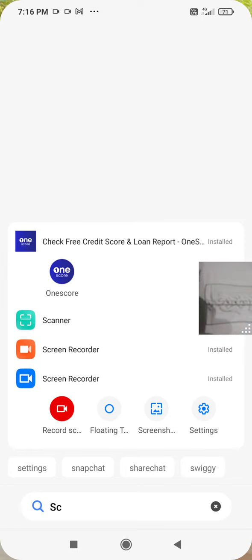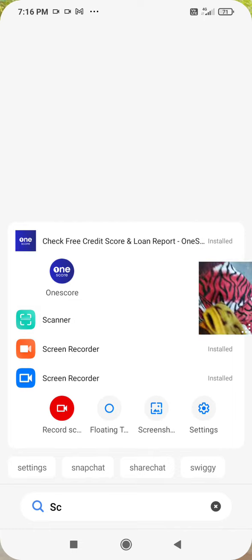The seam is unattractive because of puckering. Here are two examples of puckering. Puckering is too tight, and this one is puckering from too low tension, too loose.